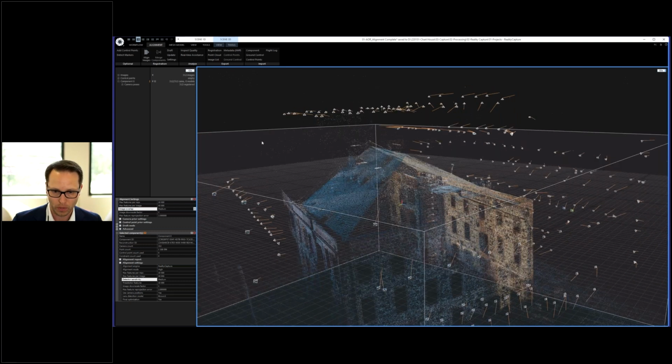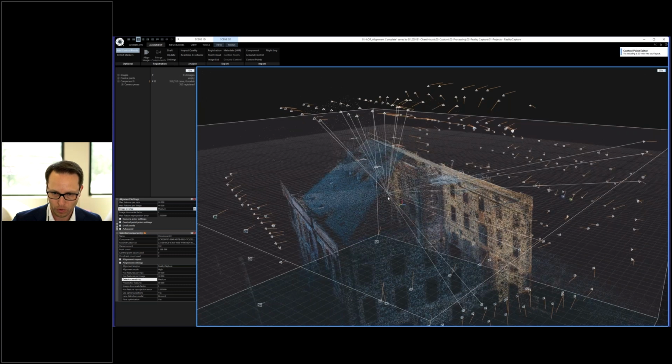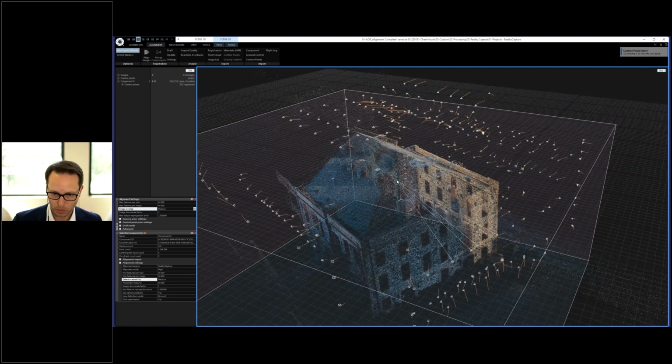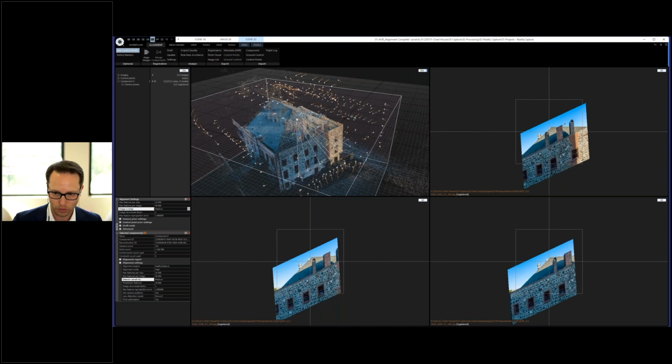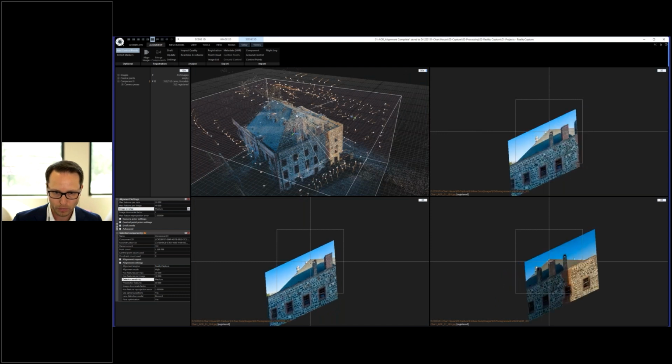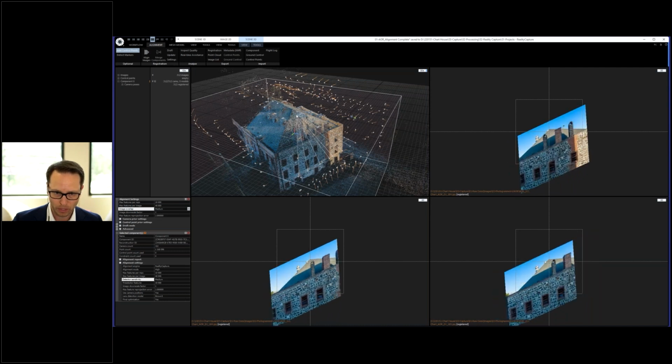The first thing is you go to the alignment tab, and then you click on the control points here. When you hover over all of these tie points, you're going to see all these projected lines, and those are projected lines from all the cameras, all the images. Also, we're going to change the view to a 1+2+2 layout. That way, when I hover over, it's going to show some of those images in the other windows. I'm going to click anywhere for now, and we can adjust that point later.